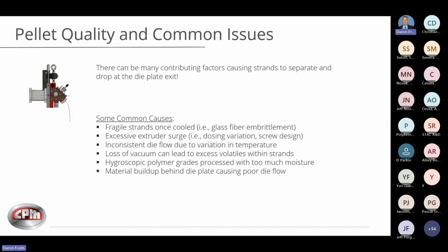A lot of times this is material dependent, because some polymers, particularly semi-crystalline type polymers, have a sharper melting temperature and their viscosity can change. So in terms of controlling that temperature, some will flow better than others from the die, where some are a lot more sensitive to any lack of proper thermal control.